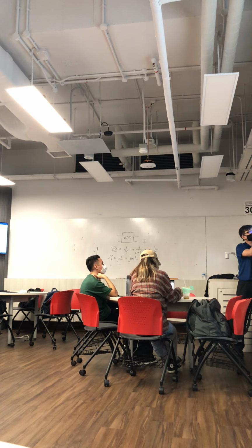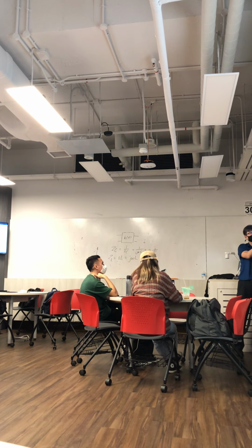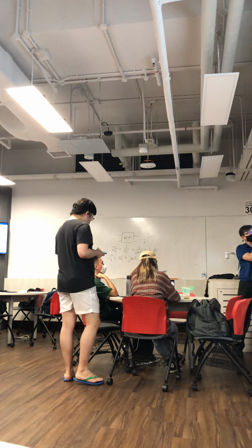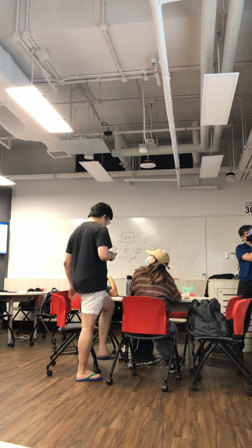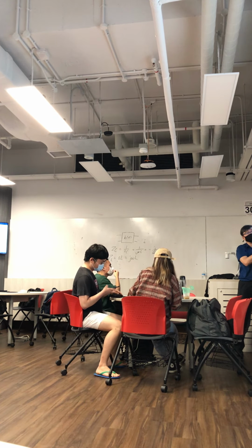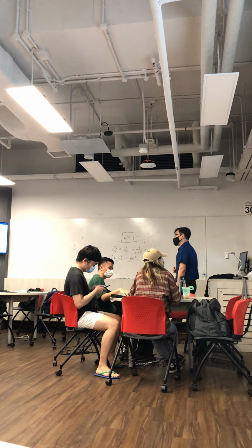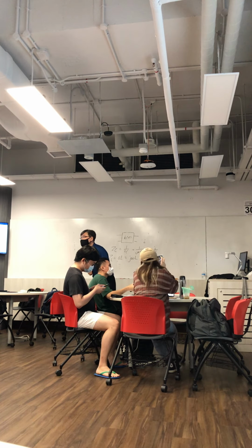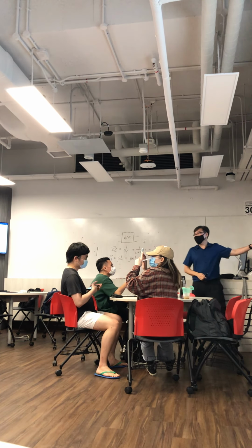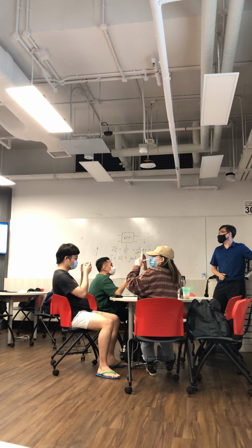Let's look at it: if you substitute s by j omega, you get this transfer function. And you can see that if I replace 1 over RC as omega p, then 1 over RC is what we call the time constant, and that has something to do with your cutoff frequency for the first order system.